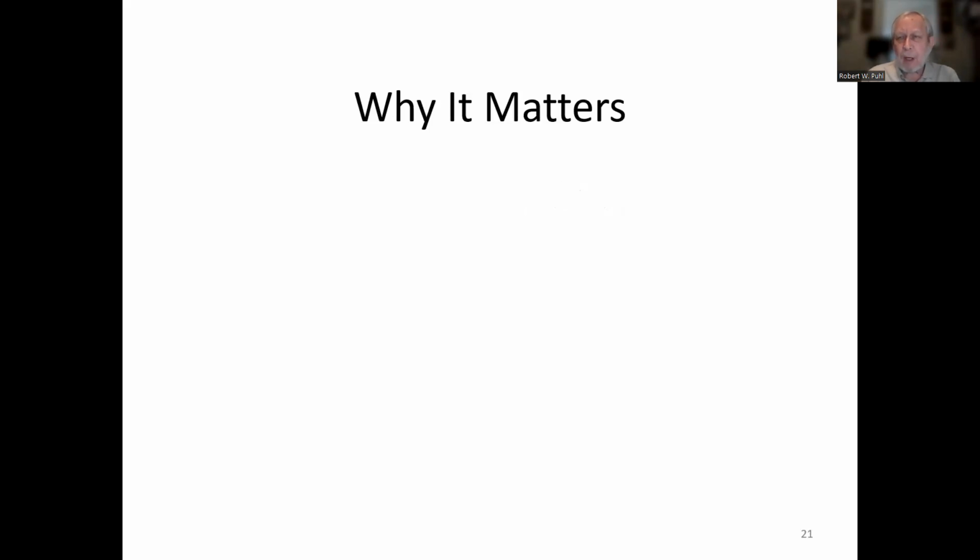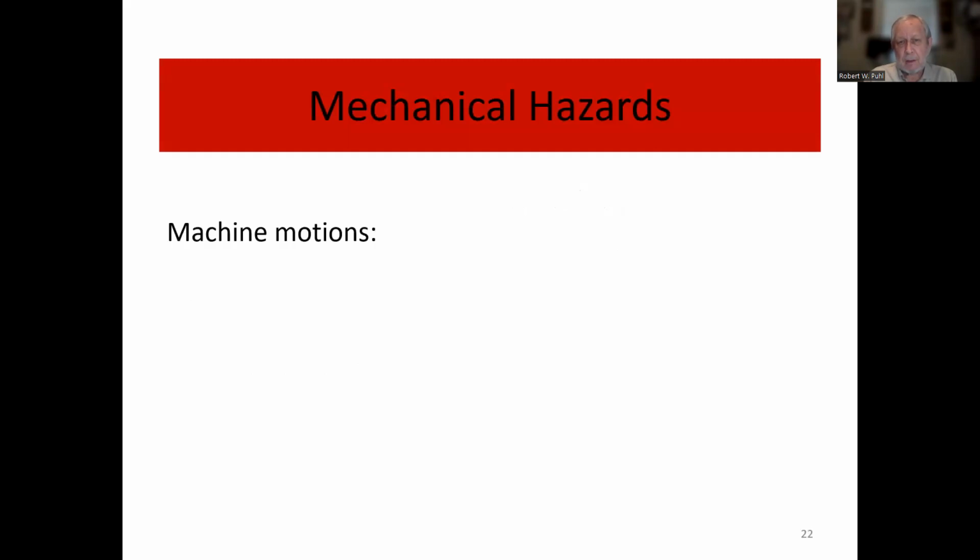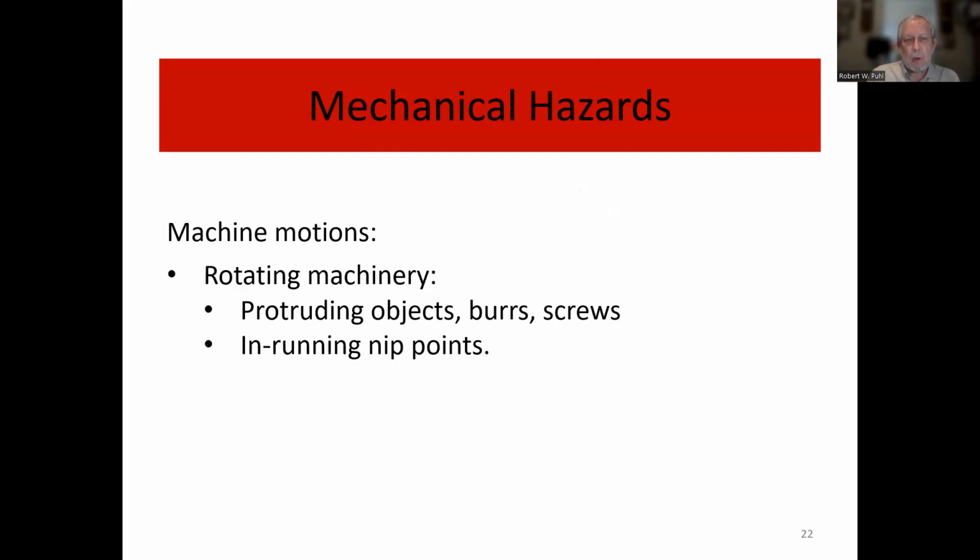Why does it matter? Why do hazards matter? Well, people get seriously injured, mangled, limbs amputated. People die sometimes. So we care about that. Mechanical hazards, machine motions. We'll talk about various machine motions. Rotating machinery, protruding objects, burrs, screws, in-running nip points.